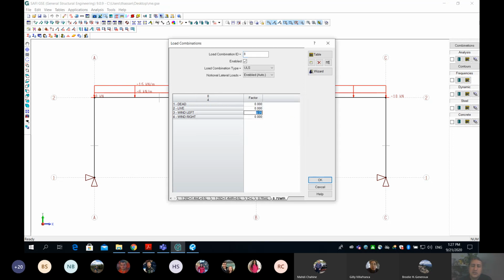And so this number is 0, and this number is 0.75. I'm sorry, guys, I've made a mistake here. What I should have done is simply go back. I'm still here, so I'm going to change this one to SLS, and I'll go back to this one. I will also change it to SLS, because those last two and this one as well are SLS. Okay, so the last three, 1, 2, 3, those three are serviceability limit state.